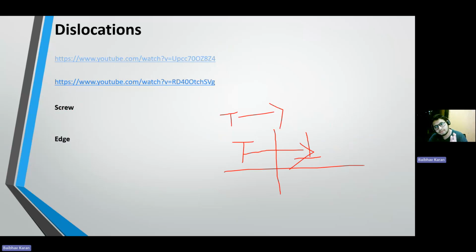So the dislocations are not present near the free surfaces, never present. Taking this concept into account, when we go into the nanoscale range and decrease the size of the material, the material will tend to be dislocation free, because the surface dislocations never stay. Due to the image forces, they will be moving out of the system. So this shows that when we move into nanostructured material, the dislocation density decreases.